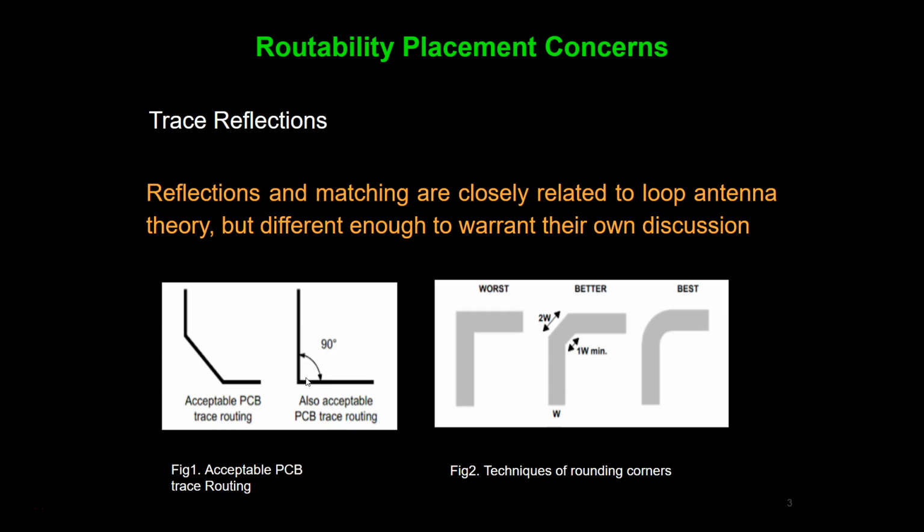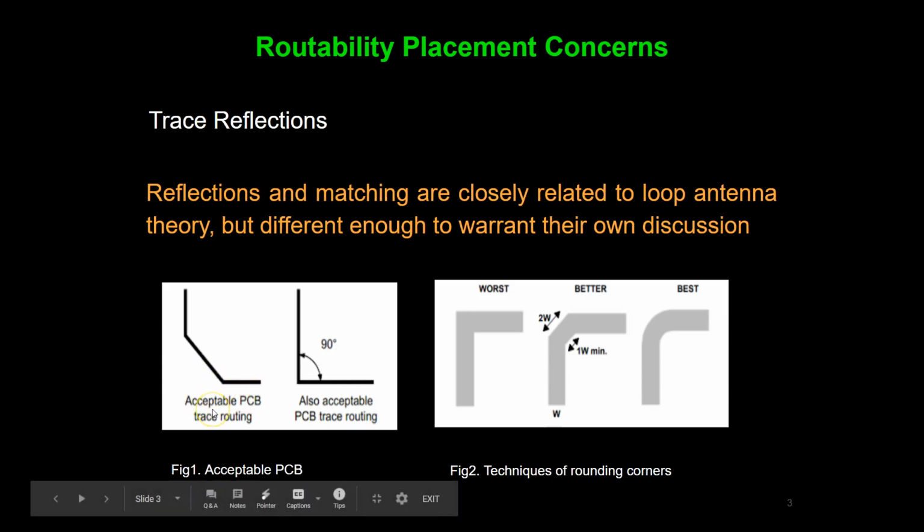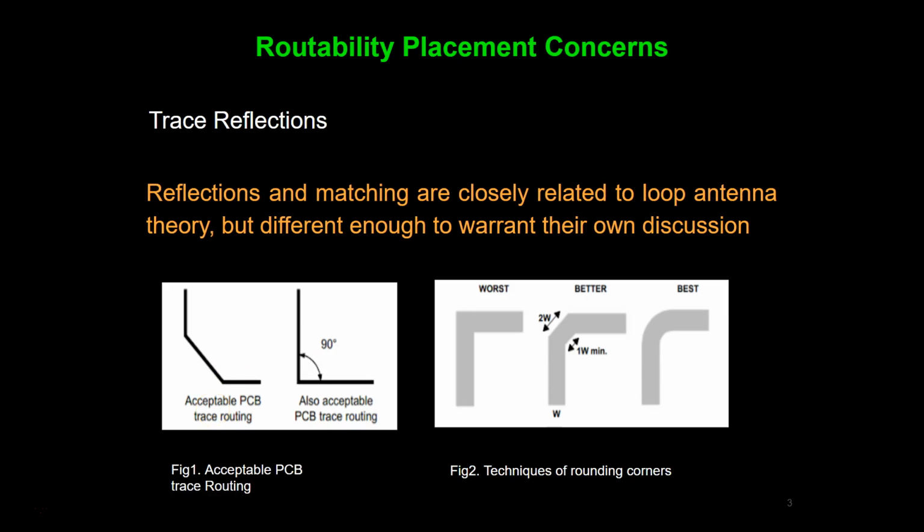As we know, not all PCB traces can be straight, so they will have to turn corners. Most software systems give some rounding effect on the traces. Here, this figure on the left shows rounding at 45 degrees, which typically reduces overall trace length. This practice frees board area, reduces current loops, and improves both electromagnetic emission and immunity. And also it looks better.